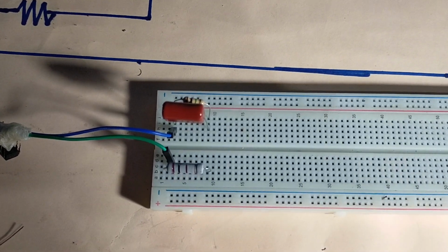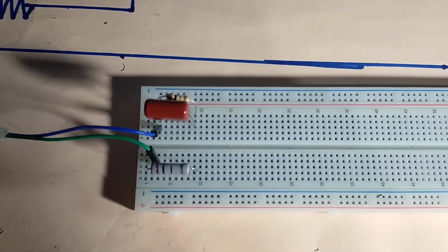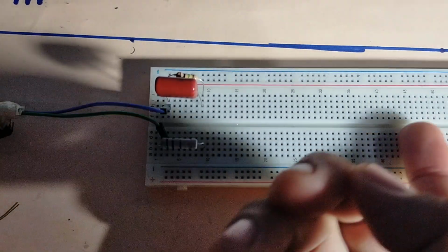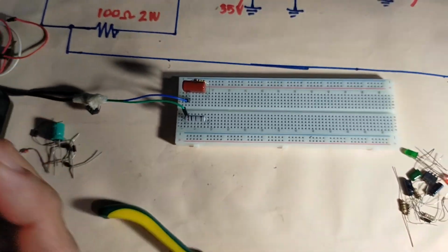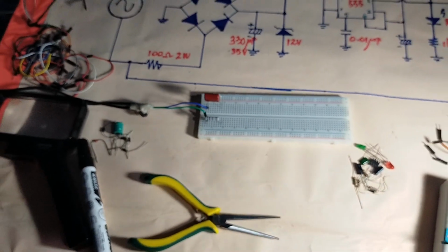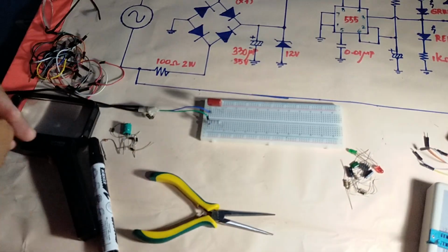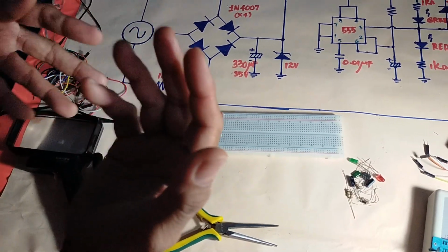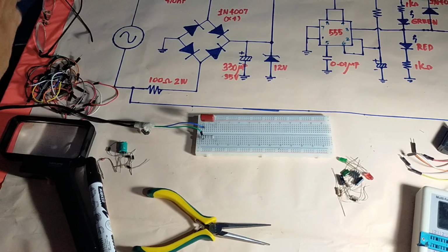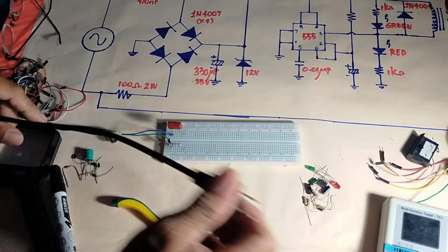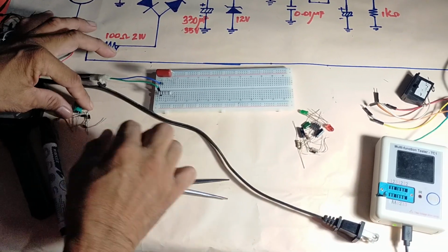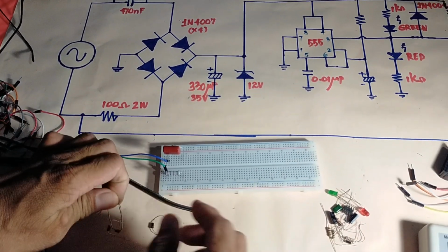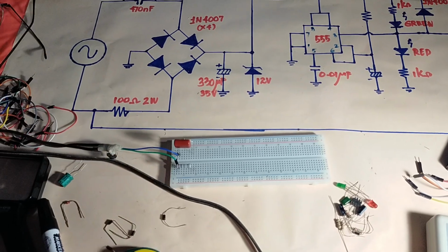Of course, the 230 volts AC from the outlet will push the current to flow entering the circuit. The current might be strong, or we call it surge current. So that must be limited to avoid this problem, harmonic distortion, that lowers the quality of the operation of the circuit. Then, there are 4 diodes, rectifier diodes, that will rectify the AC voltage into DC voltage.